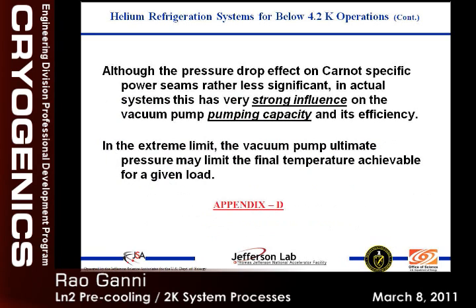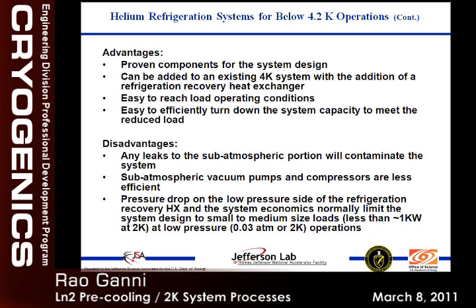So this is basically the trade-off between your pumping capacity, as your pressure drop increases, versus the refrigeration technology. The advantages: you can use an existing 4K plant, you can build a side card, and you can improve your 2K. At CDF, the 4K cold box core was designed to do this, but it has never been analyzed to this level, where we were never able to get to this level where we get only